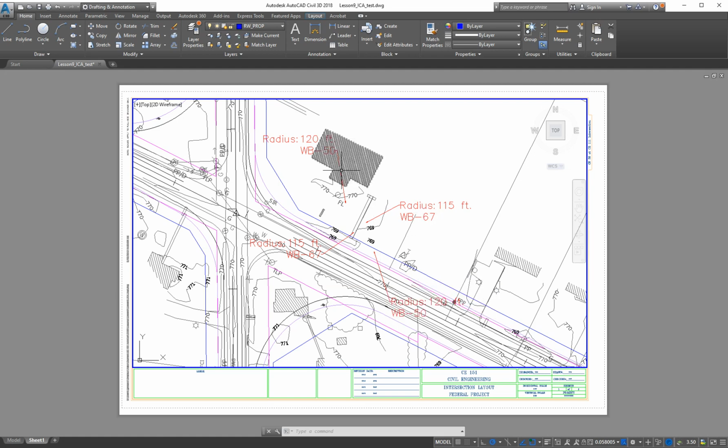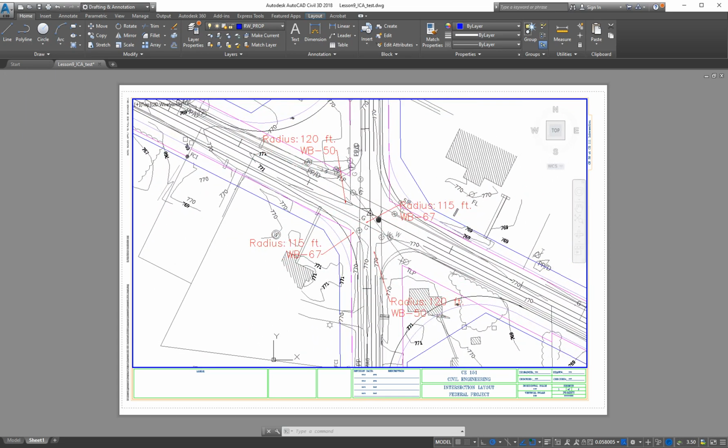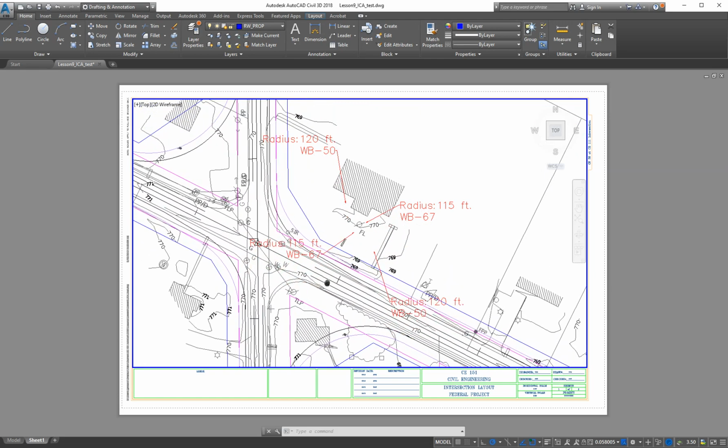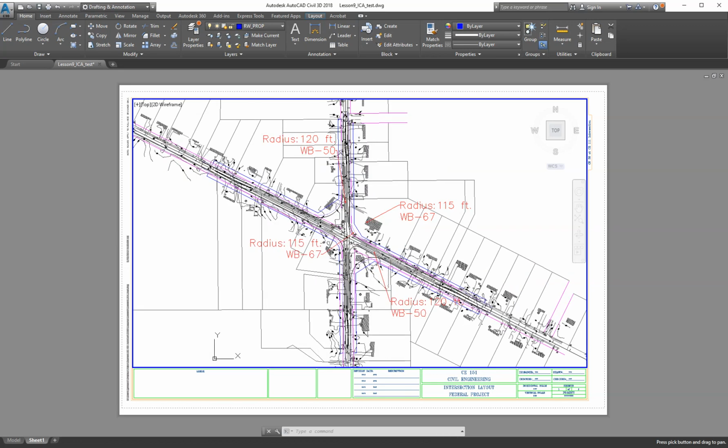That's what this stuff is, because it was in paper space. But I'm actually manipulating things over in model space. Now, just moving things around, nothing over here in model space is actually changing, but that's my view of it, right? So in that viewport, I can change how I see it. I can change what scale I see it at. I can back way up. I can zoom way in through there.